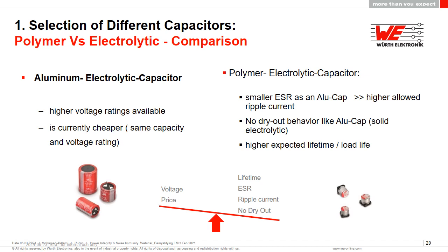But the polymers, and especially when we're talking about the standard type of converter topologies with the standard levels of voltage and current, the polymers are absolutely fantastic. Fairly small ESR compared to aluminium electrolytic, and you still pack quite a punch, so they can get you quite a high level of capacitance for that.